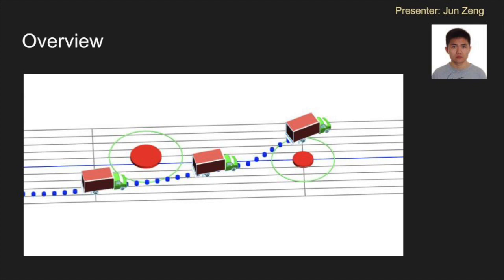Many previous works have been done on obstacle avoidance, and most of them try to track a predefined reference with fixed obstacles. This method is quite fragile to the sudden appearance of an obstacle. So in our project, we try to design a local dynamic obstacle avoidance MPC. This MPC design has three features: obstacle detection, avoidance path generation, and path following, respectively.